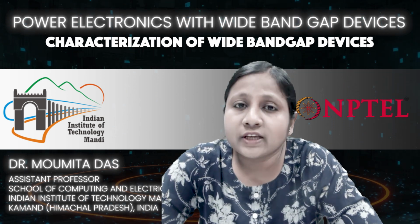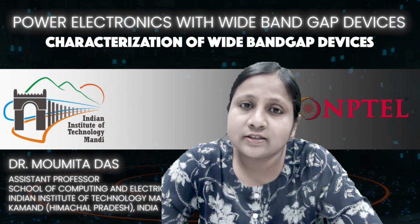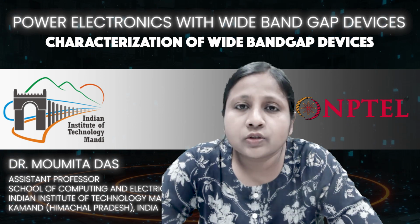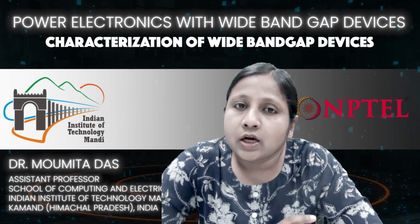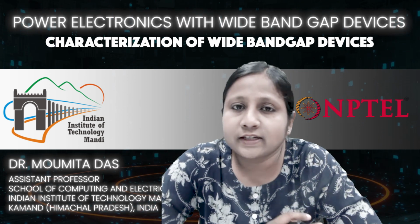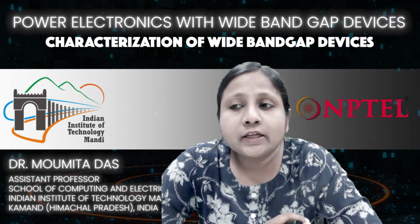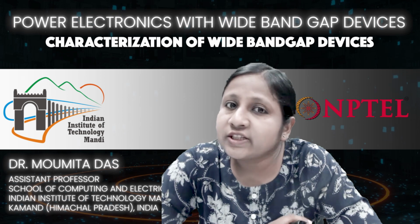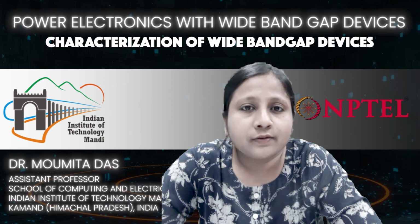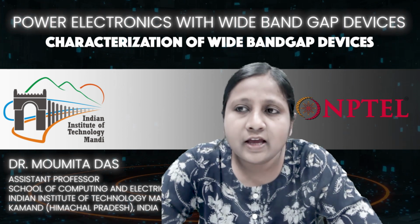If you want to see more parameters, you can download those datasheets from the website. If you download the datasheets of the same devices I showed in the previous lecture, that is silicon carbide and gallium nitride, using the same part number, you will see that for the silicon device much more information is given in the datasheet as compared to silicon carbide and GaN.